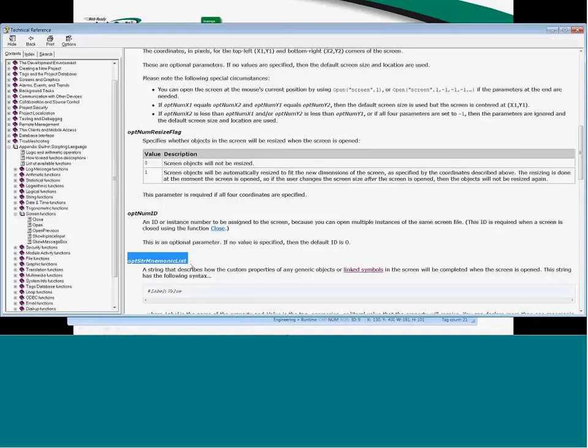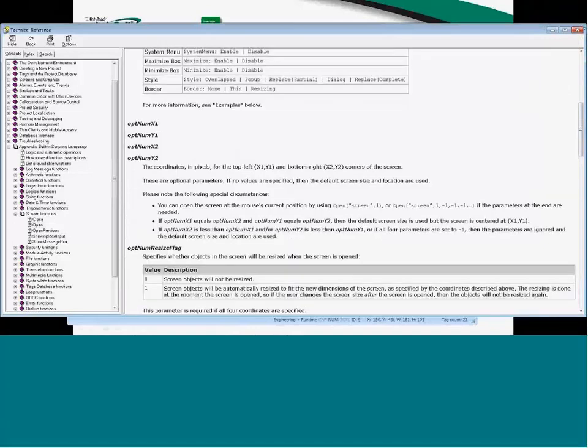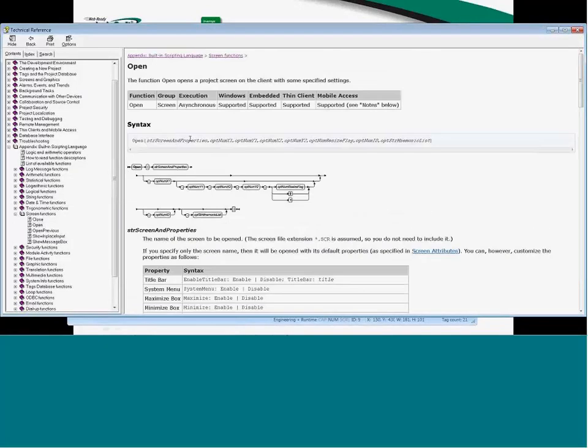Well, then I can open up that exact same screen, but open it up as instance number 1 or number 2 or number 3, and then pass it an entirely different set of tags, and I can use and reuse that screen repeatedly for as many pumps as I have. So let me give you an example of how we did that. And again, it's just following this list here of the parameters.